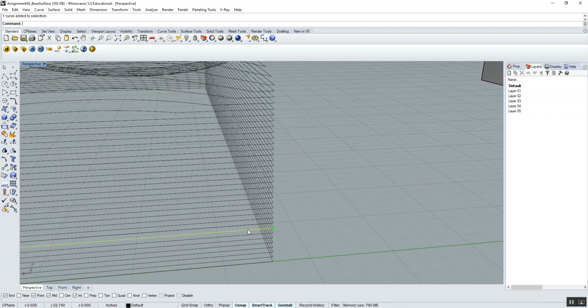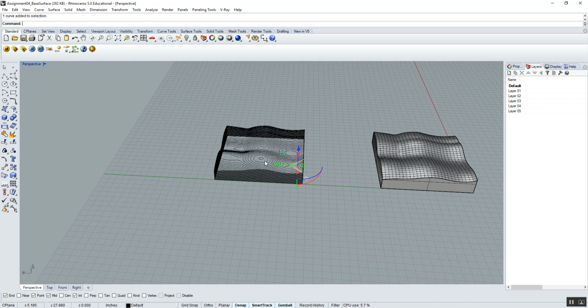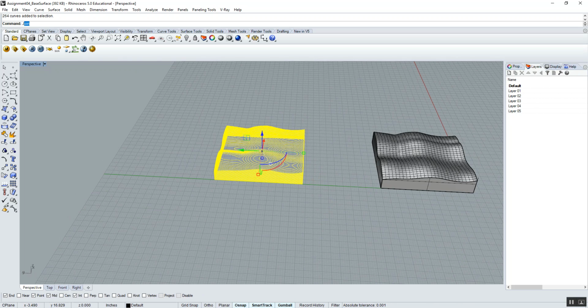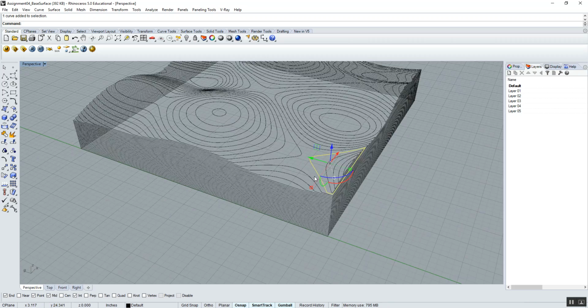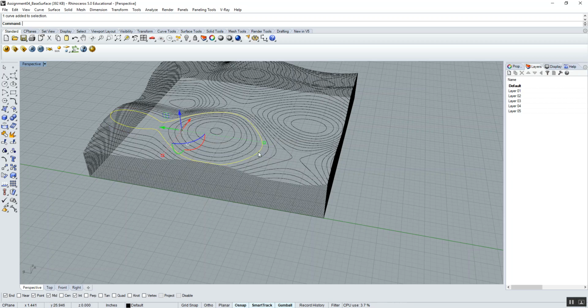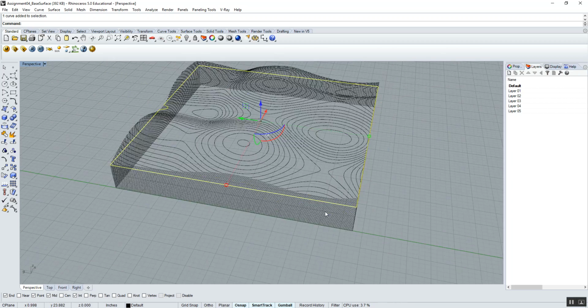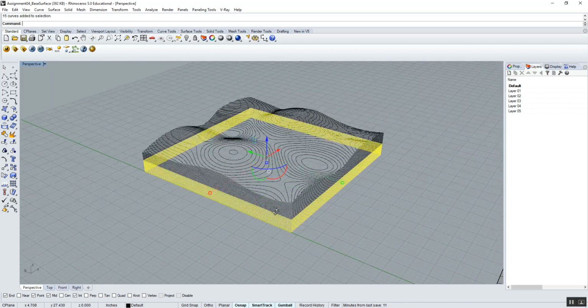Now, one thing that's important to notice is that as I select some of these edges, they are individual lines. We could simply select all these and type in join. Any objects that are fully closed will then be joined as closed polylines, and that should be all of them. There should be no actual open objects that exist. And you'll see a whole lot of them. They're just a whole bunch of squares on the lower portion here.